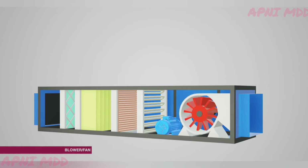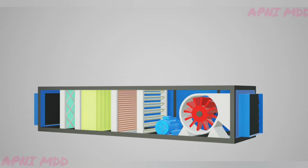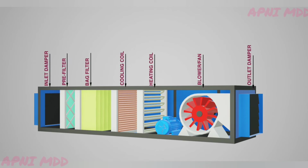The final component of the AHU is the fan. To push the outside air to the building spaces, a fan is provided in the AHU, which pushes the outside air into the building with the help of the ventilation system ductwork. These fans can be either single speed, dual speed, or can be equipped with variable frequency drives to control the speed of the fan. Fan is placed at the end of the AHU. The next component is the outlet dampers. This is similar to the inlet dampers. With the inlet and outlet dampers, AHU can be completely isolated from the ventilation ductwork when it is not in use.